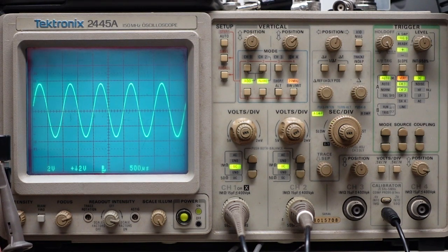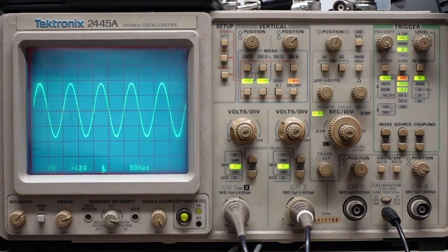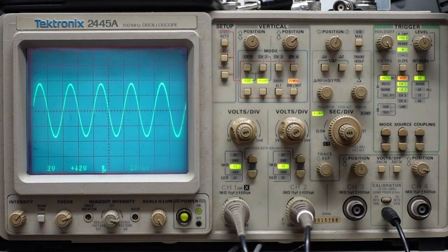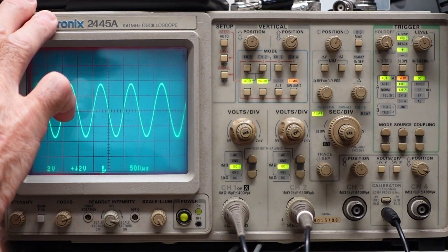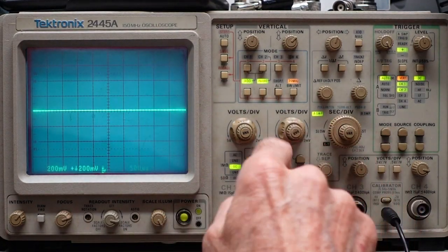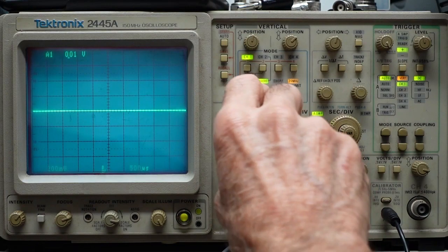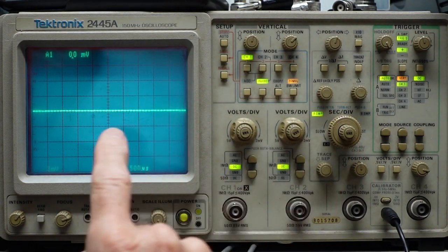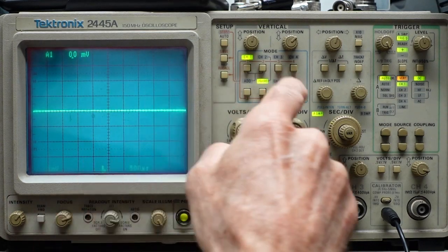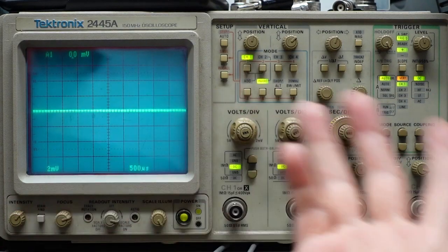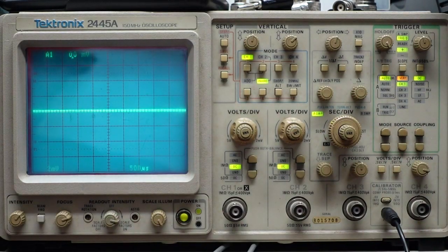The other thing I want to point out on this scope before I set up multiples is there's a button that says bandwidth limit. Now, this is a 150 megahertz scope, and I'm going to take both the inputs out, and we're going to look at channel 1 only, and I'm going to crank the sensitivity way up, and what you may find is you get noise. See how thick the trace is? That's just noise pickup, but when you have a probe on there, it can be worse.